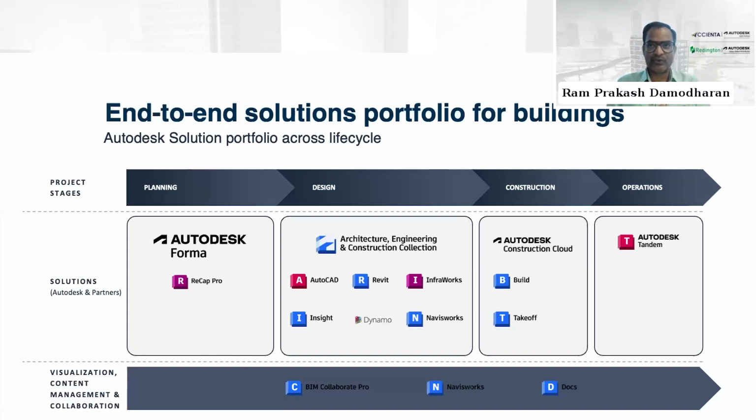But if you have a project which has already begun with BIM, you're going to put all the data into it, including the real data from sensors, the manufacturer's list, the amps for the current, the luminance of lights and so on. It gives you very clear AIM, asset information management, and it can also deliver the details wonderfully for any life cycle assessment, when you want to hand over the documents to the operation stages, which can tell you where the problems are occurring, when the next service is due, and what systems are in place.